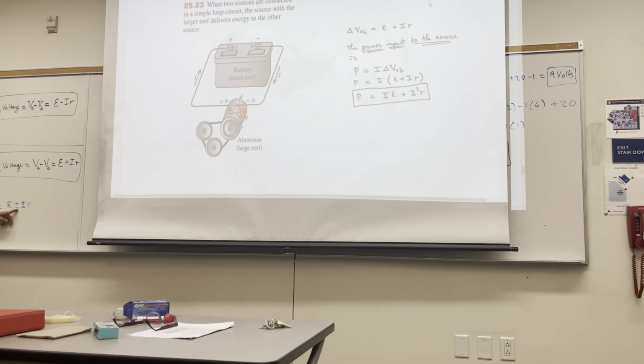So when do you use the minus? When do you use the plus? Well, given this discussion, you use the minus when the current is out of the battery, out the positive terminal. And you use the plus when the current through the battery is entering the battery at the positive terminal. Entering as opposed to leaving.